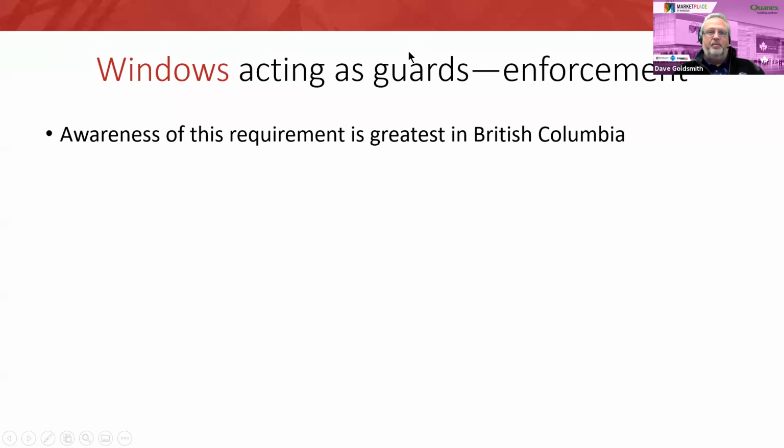Well, at one point I thought that if you tempered the glass, it was always going to meet guard loads. But then I found out there's a finite element method, and really the only way to analyze it properly as an engineer is by using finite element analysis. An engineer pointed me to a particular software, and it will not meet guard loads at 3 millimeter annealed, not even the infill load, not at any size. I know it needs to be tempered. And we have some slides on using that software if we wanted to move to them.